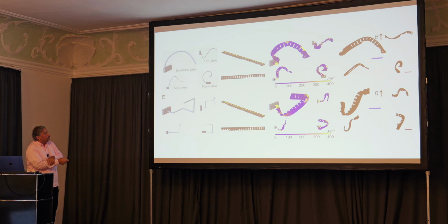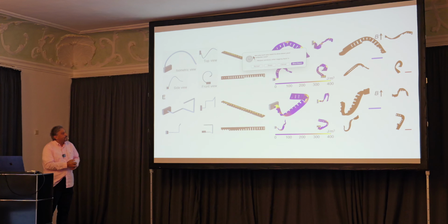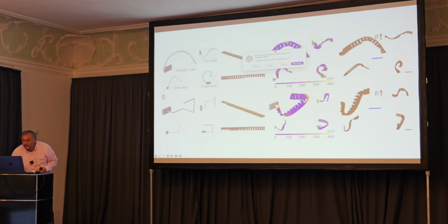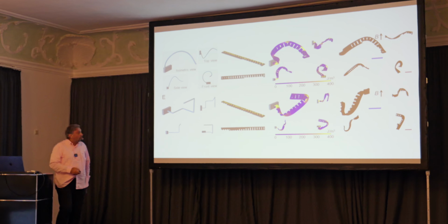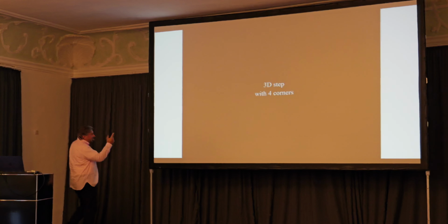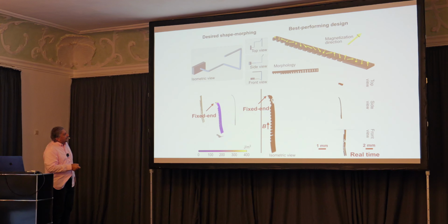And the good news is it's a solvable problem, and you see the profiles. And here we use a magnetization fabrication technique that locally we can laser heat and demagnetize the material and apply the direction and magnitude. And then at room temperature, basically, the magnetization will be frozen, so we can locally magnetize like bits or voxels precisely using a new technique that we developed. So then, again, you can start from the sheet with the given algorithm, fabricate it, and this is